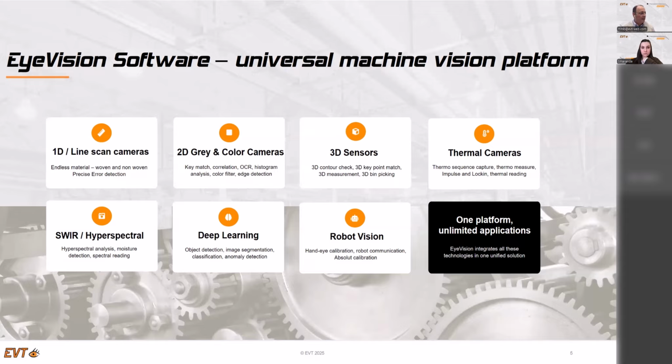And of course, the good thing is you can get a lot of GigE boards, which you can add to your PC easily over PCI Express if you have multiple cameras, to allow to use multiple cameras at the same PC, which is really nice if the bandwidth is in question, or if you have multiple cameras, like let's say 10, 12 or whatever cameras.